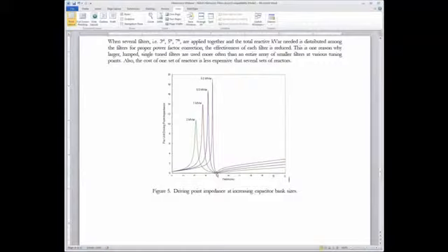And that brings up another point. That's why we typically slightly detune our filters. So when I'm saying 5th harmonic filter, in almost every case, it's going to be somewhere between 4.7 and 4.9 in its tuning, for the key reason that if I ever blow units in it and it starts shifting upwards, I basically can keep this first parallel resonant point from hitting right on the 5th harmonic, because if it did, that is not a good condition that you want to have happening in your facility.